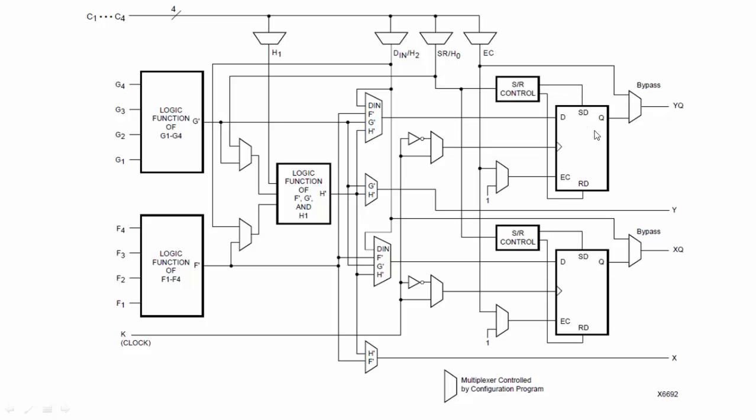In case you want to store them and you want the output only when a particular clock applies, or after some time, for that purpose you can store the output at one of the D inputs of the D flip-flop, and whenever you need, you can provide a clock. You can provide the clock coming from here, and you can make it available right here, or you can also bypass it from the D flip-flop, right? And the clock generator is here. This is the clock line.